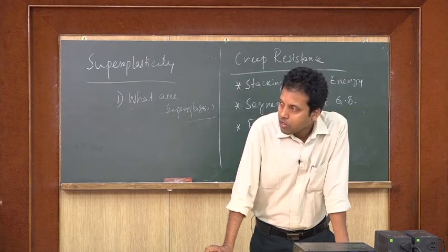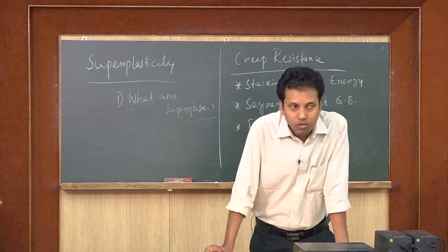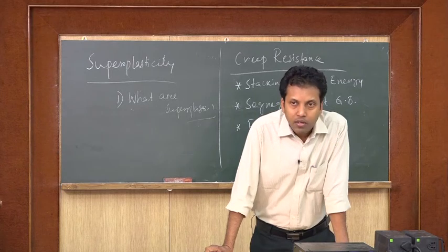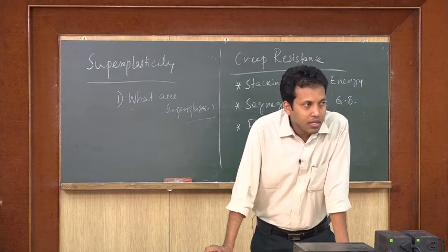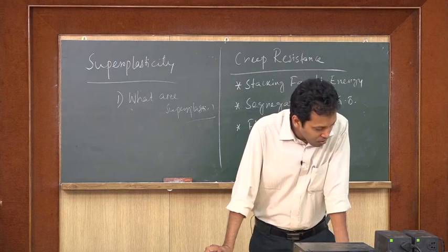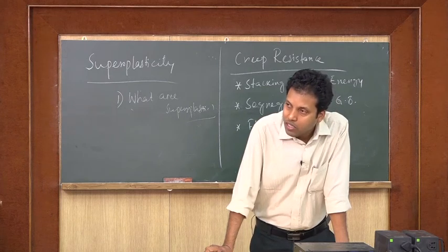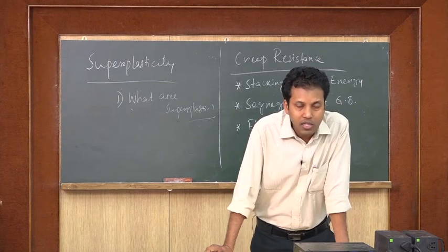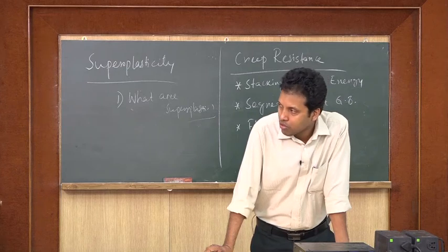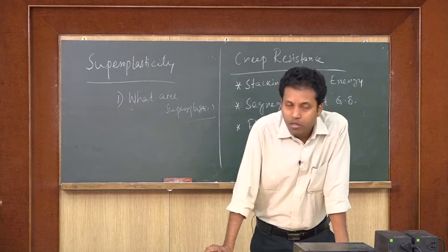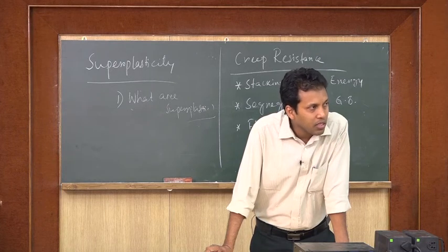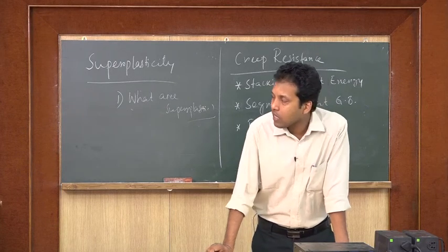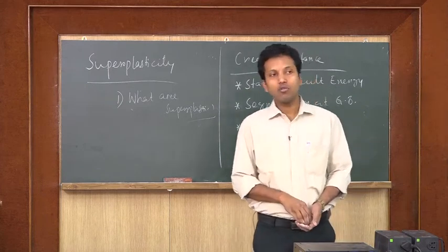During creep deformation we have climb. If I reduce the stacking fault energy, then the dissociation to partials will be reduced, and that way cross slip can be affected. High stacking fault energy means it is easy for a material to cross slip.